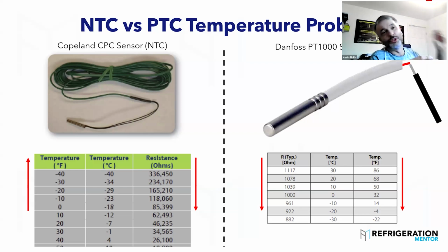Let's say you've got some really funny readings on your sensors. If you take the probe off at the cooler, twist the wires together and take them out of the controller, do a resistance test on it, see how much resistance is just in that cable. And that'll give you a guide as to how much you need to offset your probe by to get the right reading out of it. There's an argument to say that a PT1000 isn't the best for huge cold stores, but you are kind of stuck on certain controllers with using it. So it's worth bearing in mind for the cabling.